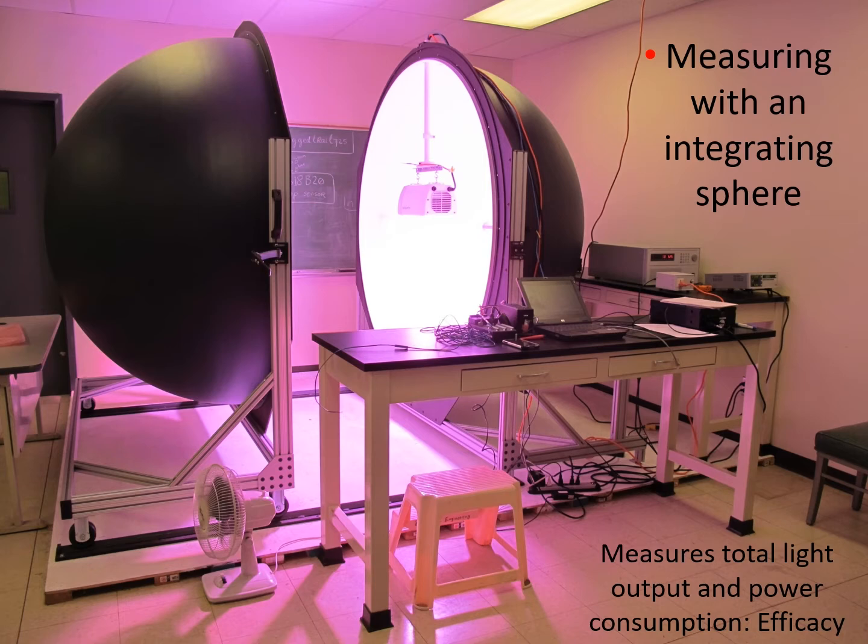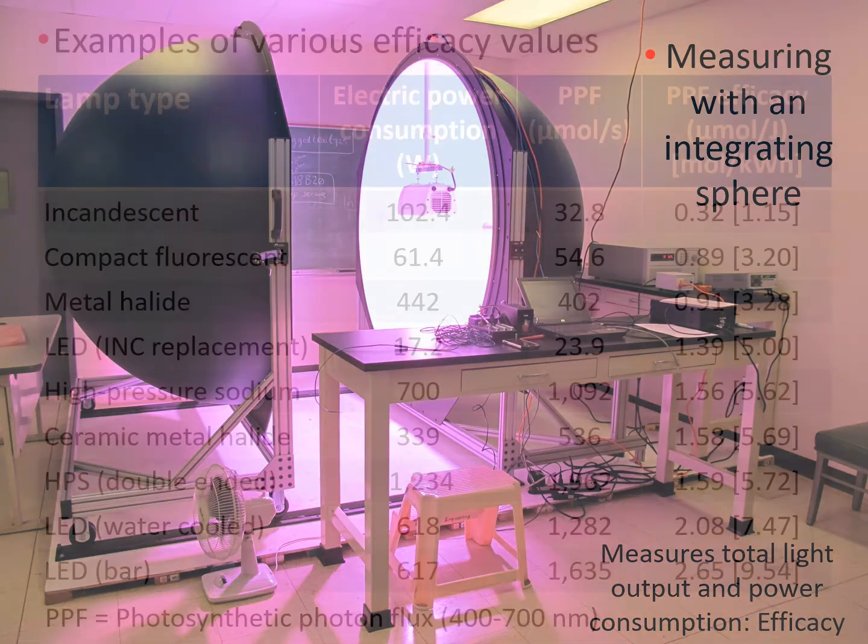If we want to measure the efficacy of a particular lamp or fixture, we need to use an integrating sphere, as is shown in this slide. The integrating sphere is closed during the measurement, allowing it to capture all the light that is produced by the fixture. At the same time the light output is measured, the electric power consumption is recorded. Combining these two measurements allows us to calculate the efficacy in micromoles per joule of the lamp or fixture that was tested.